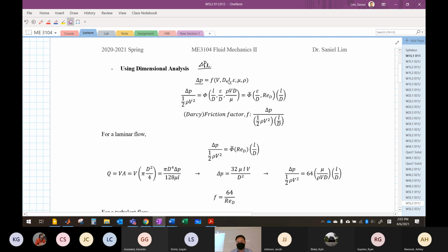When you do the dimensional analysis, you will find these expressions. Of course, you may not have this constant 1/2, but in the video I explained that we want to tweak the shape of the dimensionless group in terms of the common dimensionless groups we know. Reynolds number is the most popular one. Another one is the dynamic pressure, which we normally write as 1/2 rho v squared.